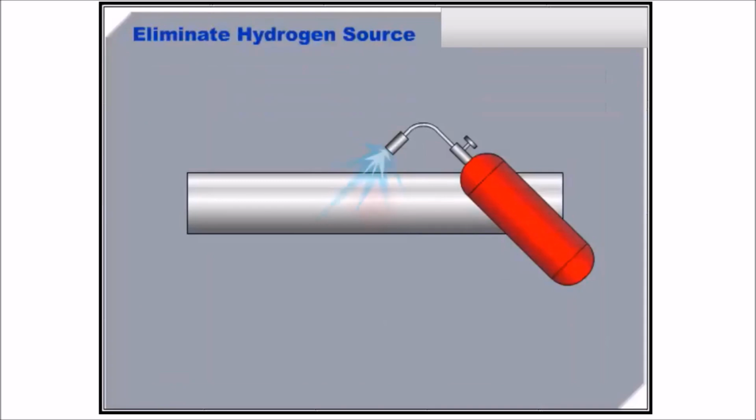Preheating the base metals is also effective in eliminating hydrogen pickup, because hydrogen will diffuse out of most metals at temperatures of 200 to 450 degrees Fahrenheit. The methods noted can all aid in reducing the possibility of hydrogen cracking in those metals which are susceptible.